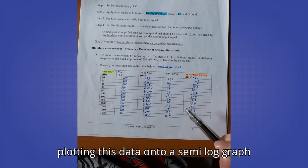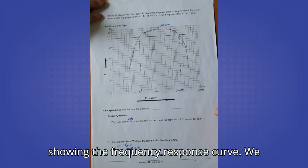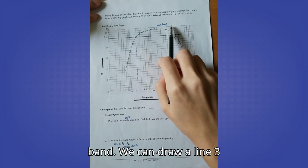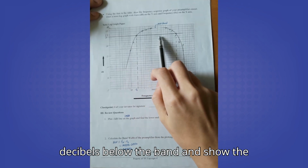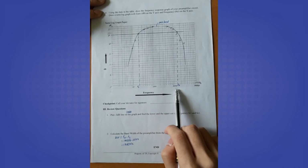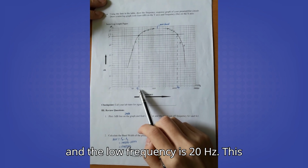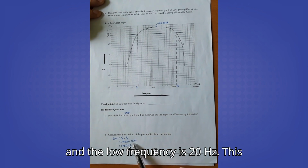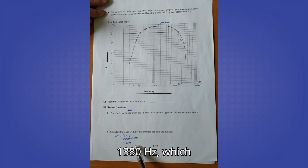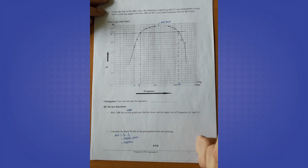After plotting this data onto a semi-log graph showing the frequency response curve, we can see that the 27 decibels is the pass band. We can draw a line 3 decibels below the band and show the cutoff frequencies. From my graph, the high cutoff frequency is 1400 Hz and the low frequency is 20 Hz. This results in a bandwidth of 1380 Hz, which is basically 1400 Hz minus 20 Hz.